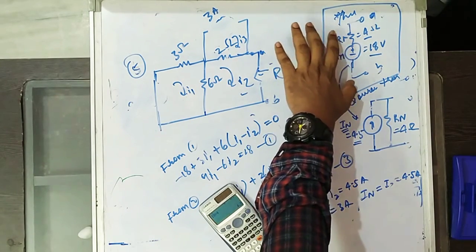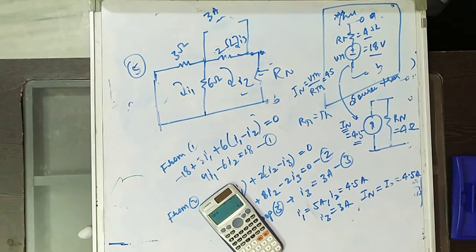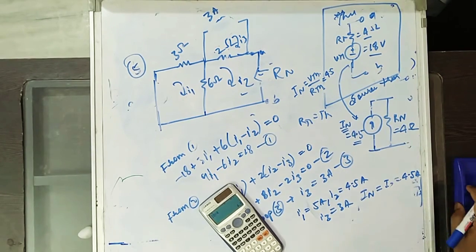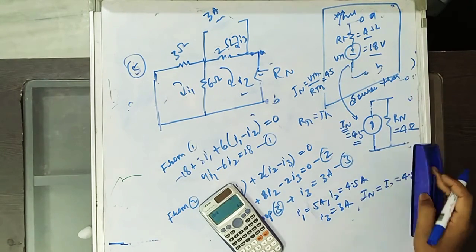Now if you source transform this Thevenin equivalent, you'll get the Norton circuit. Or else, to clarify whether you got the Thevenin equivalent correct or not, you can do the Norton equivalent, and if you source transform both, you'll get clarification. Solving methodology is like this. Okay, now we'll solve. So this is based on category 1, only having independent sources.